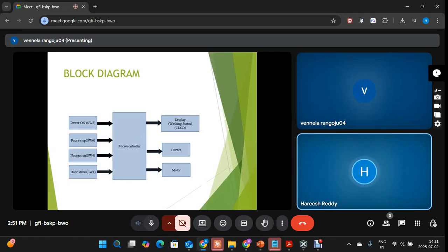The microcontroller also uses its internal timers to manage the time-based operations of different washing phases. We configure interrupts to handle events like button presses or timer overflows, allowing the system to respond instantly without continuous polling. The architecture makes the system modular, responsive, and easy to debug. All work is in sync under the control of the microcontroller to simulate the behavior of a fully automated washing machine.